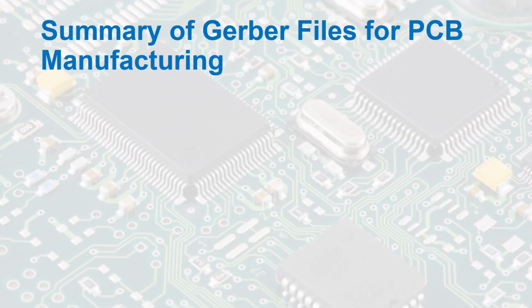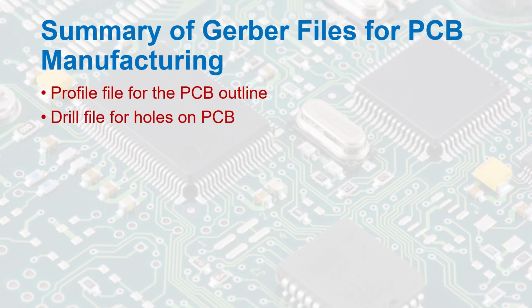In summary, Gerber files are the standard manufacturing files used to communicate a PCB design to a fabrication facility. Each file defines a specific physical layer or feature of the board. Profile file defines the external shape, dimensions, and cutout features of the PCB, guiding the board routing process during fabrication. Drill file specifies the locations and sizes of all drilled holes, including component mounting holes and vias.